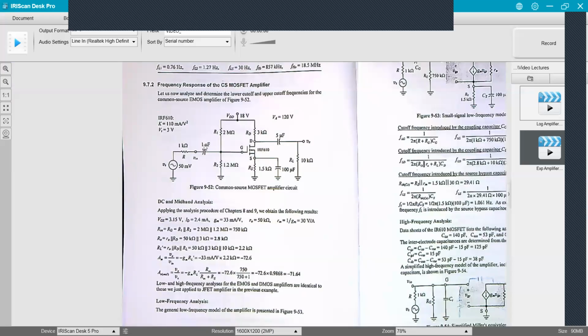And this is a capacitor, so there's no DC current flowing through there. So all the current that flows from this 18 volts flows through here to ground. That would be 18 volts divided by, I think I just talked about that a minute ago, 3.2 megohms. So it's going to be like microamps, 6 microamps. So we got about 6 microamps here. And what was it?